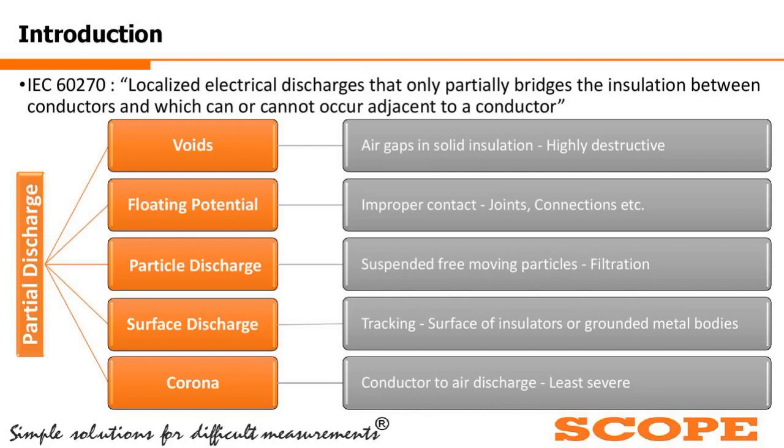These are happening generally in liquid or gaseous insulation. So it can happen inside the GIS or inside the transformer. And once again, it could be a very common type of PD, because inside the transformer or inside the GIS, there could be foreign objects getting generated. Let's say for the GIS, if the breaker is operating at that time, some metal vapor will get generated due to the arcing happening in the breaker chamber.